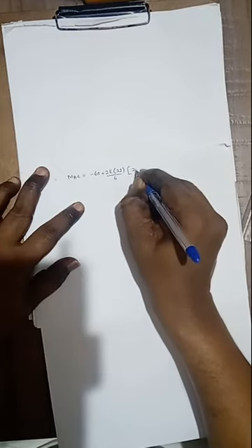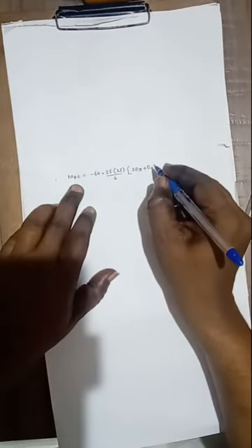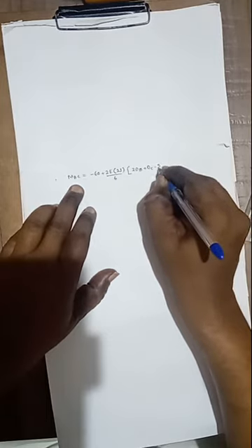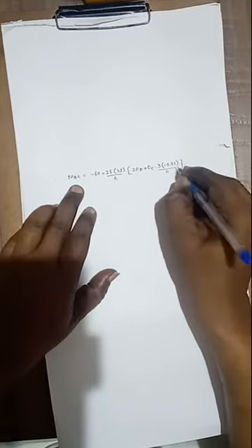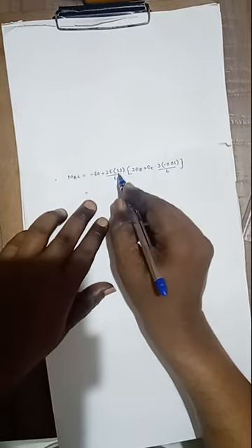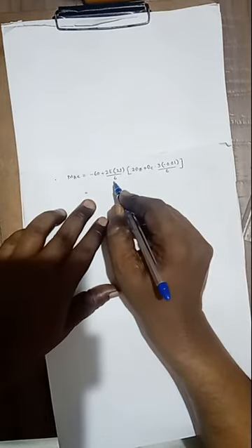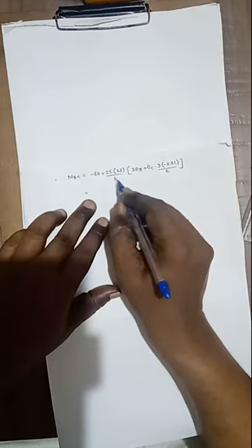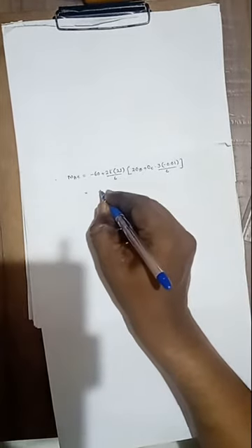Inside the bracket, 2 theta B, here the near end is B, plus theta C minus, here delta is negative, minus 3 into delta, that is minus 0.01 divided by L. Then if you simplify this, MBC equals 2 into 2, 4 into 2, 8 divided by 6, that is 4 by 3 into 4000. Here we will get after simplification,